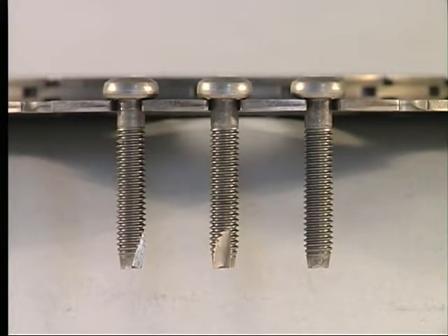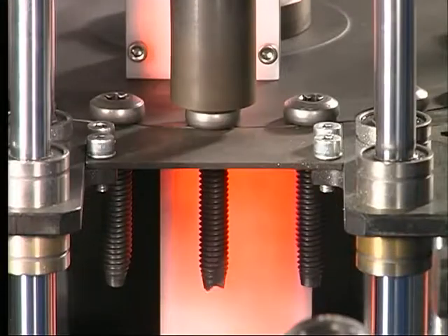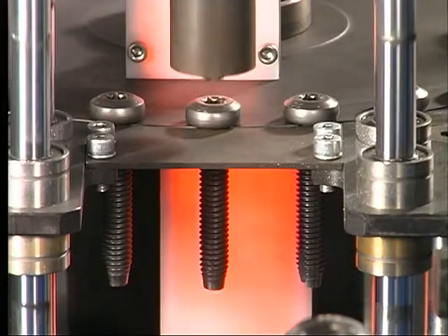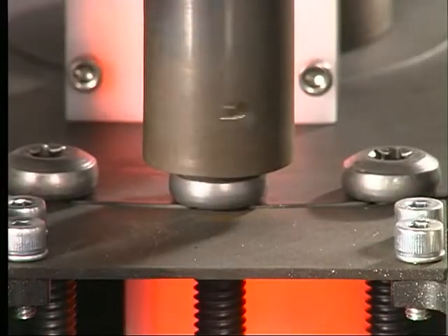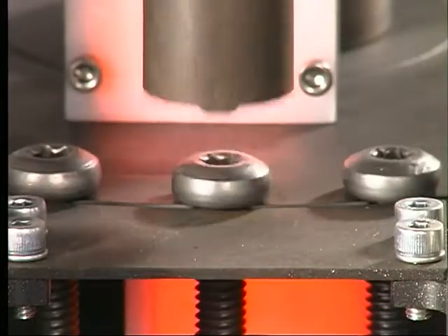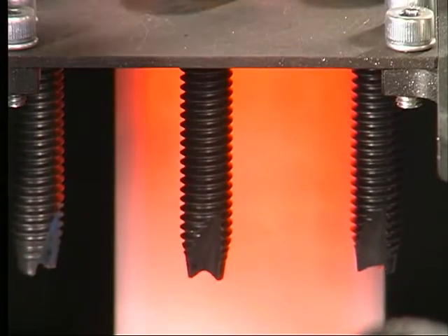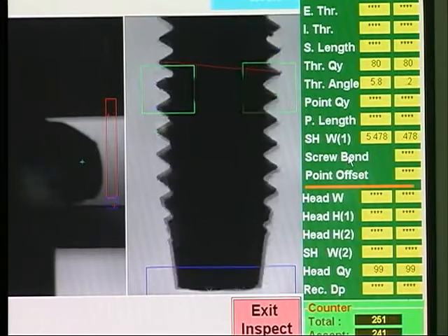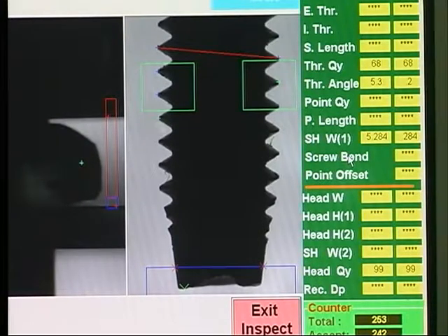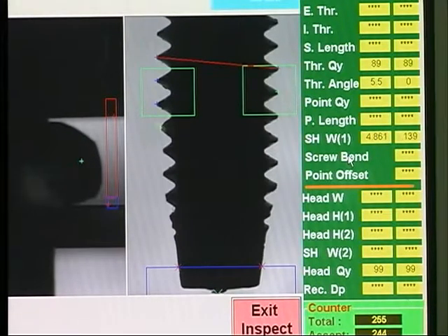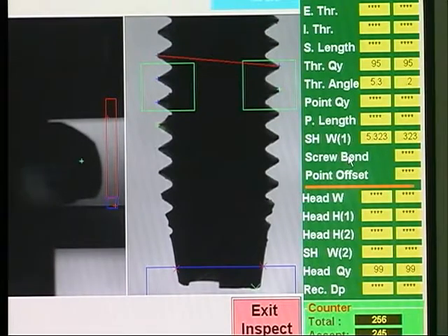Screws with problems of a hole point, a bent body, or a point cut cannot be correctly identified from a single image angle. Our CCD machine has the capacity of grabbing multiple images of a screw from different angles. The press-down mechanism rotates the inspected screw by 180 degrees. Meanwhile, the system grabs still images of the screw from up to 6 different angles.